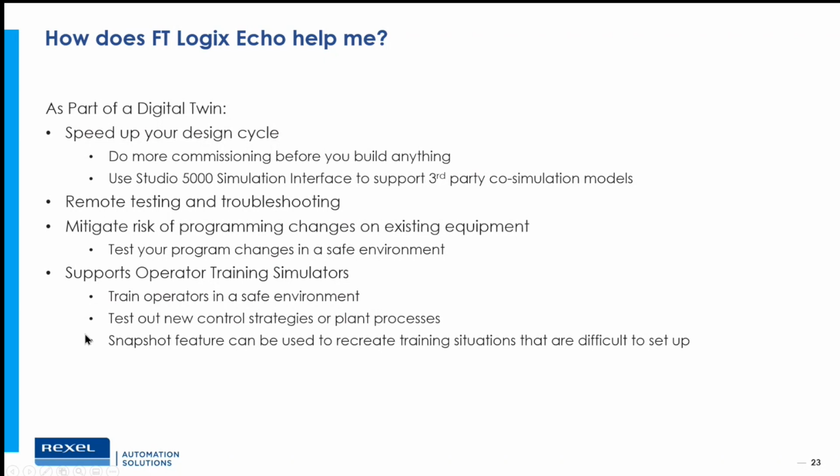Another idea, you might be doing remote testing and troubleshooting. Maybe you build your machine and you have your digital twin of your system, and your machine gets out in the field, and somebody says, hey, it's doing something kind of funny. You can actually spin up your model, your simulation, and your instance of Logix Echo, and do some troubleshooting to figure out what's going on without having to go on site, and then maybe implement a fix that you could feel more confident sending out there. And again, it's going to mitigate your risk of everything, really.